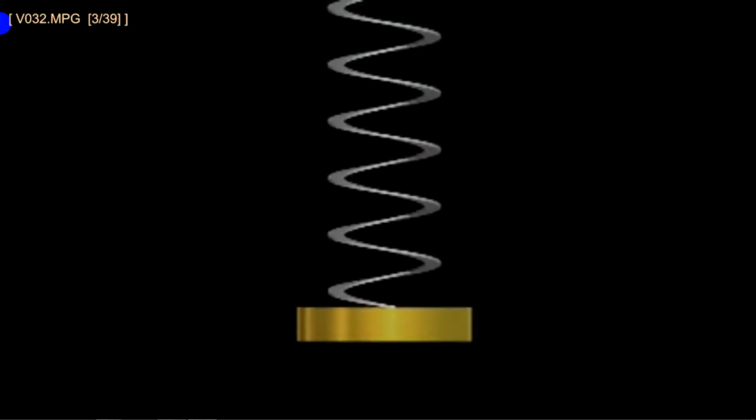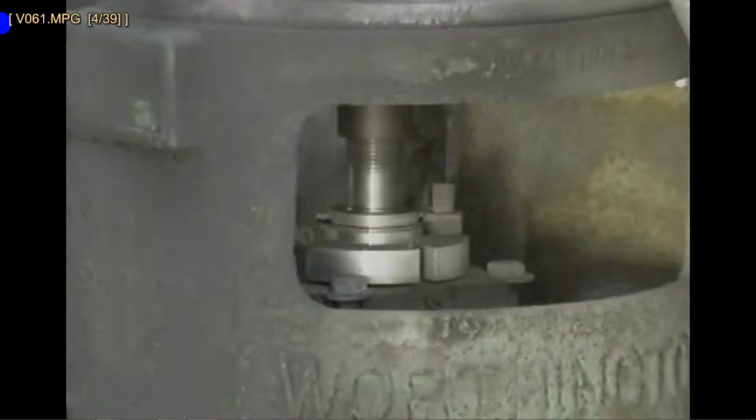When this block travels from a starting point between two extreme positions and back to the starting point, it has completed one cycle. When an object vibrates, the velocity of the vibration changes constantly. When this block moves past the center position, it's traveling faster than it is when it reaches one of the extreme positions. Because the velocity of a vibrating object is constantly changing, the highest velocity measurement is generally used or displayed. This velocity is known as the peak velocity. A vibrating object's acceleration is constantly changing, so the peak acceleration is what's used or displayed.